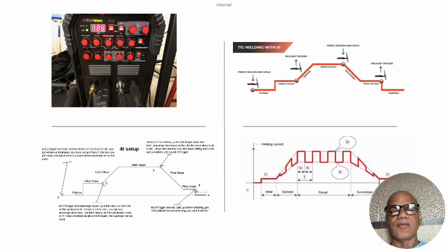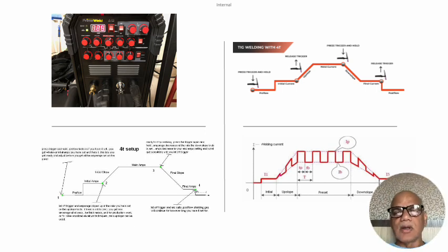And there are different types of controls we give. Once you press it, it gives only the gas. The second time you trigger the torch on your TIG, or make like 2T machines or 4T machines, then you get the current to the initial current and upslope and then main current. Once you trigger it, the downslope starts. Another time you trigger it, the current stops and the pre-flow or post-flow continues till the time the welding requires to be shielded. So this is the way you adjust all your